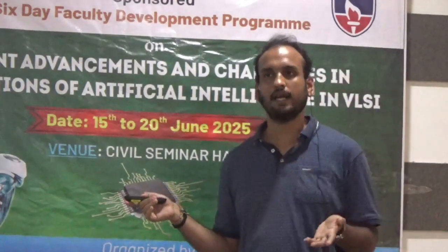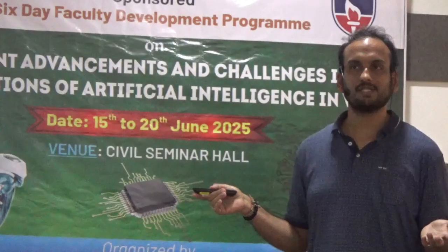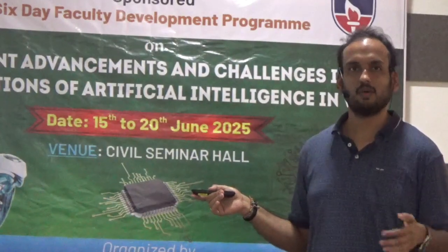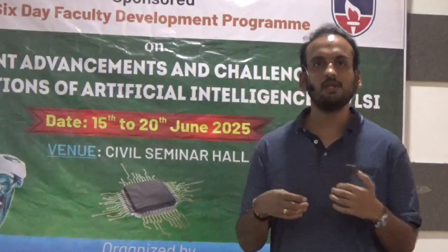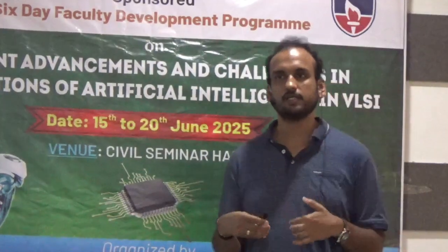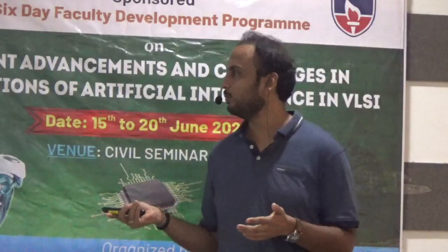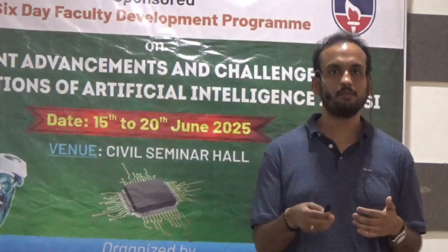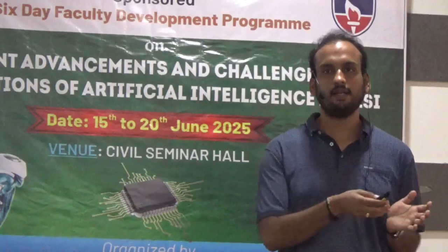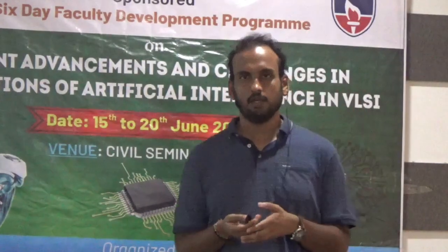You can go for different modulation schemes like QAM 64, QAM 128, 256 QAM. Like that you can increase the higher data rate. Another thing is carrier aggregation. So you can use different carriers in your communications, and then you can exploit the bandwidth. And full duplex and MIMO is another way. MIMO means you require multiple inputs and multiple outputs, and finally you get more bandwidth or more data rate from using this multiplicity.